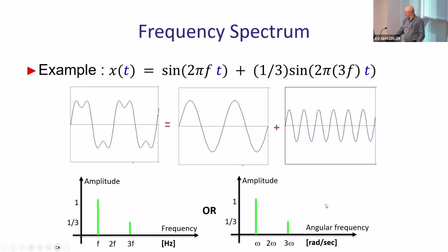The farther to the right that bar is, the faster the frequency, which means it's changing much more frequently, higher frequencies, all right? And typically in regular signals, when you're doing a Fourier transform, this is the kind of plot you will get from a Fourier transform or Fourier series. You'll have just a spectral diagram with many, many bars in discrete time, or a continuous curve of frequency response for the continuous case, continuous Fourier, all right? So this plot just tells you how much of each sinusoidal component in that signal you have.